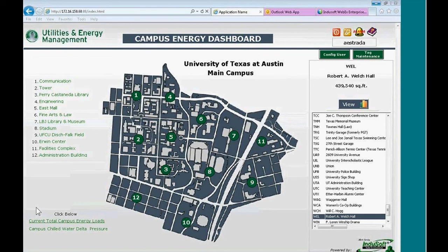But the fact that we can go after data in the historian takes the load off of the typical way that trending is done with some of our other automation systems that may access a PLC directly for data, and then we have to set up another database to log that data.